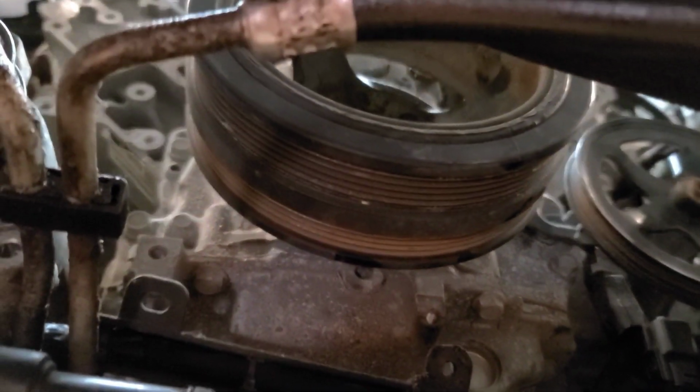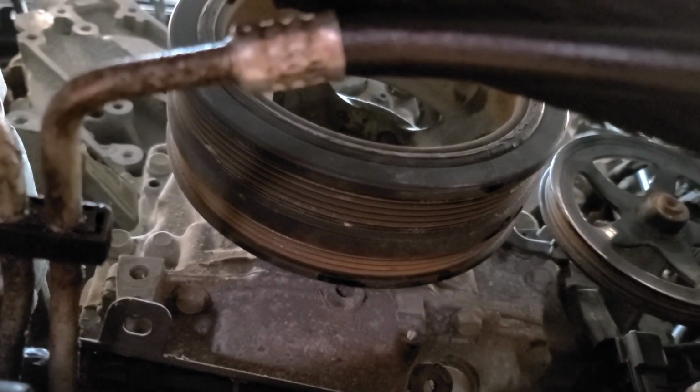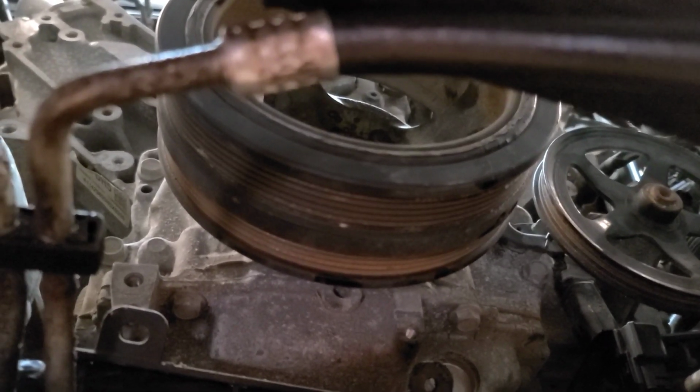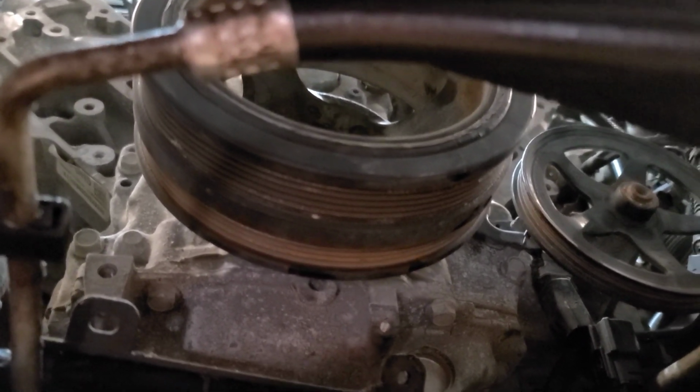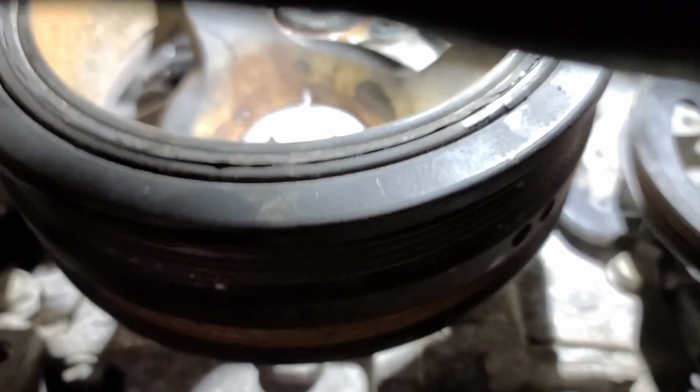And we're going to have to estimate it because I don't have an angle torque wrench, and it is frickin' tight. You'll need a 4-foot bar on this thing to turn it. So I've marked the balancer where it is with a black mark on the bolt flange. Can't see it very well there. Maybe if I get up like this.